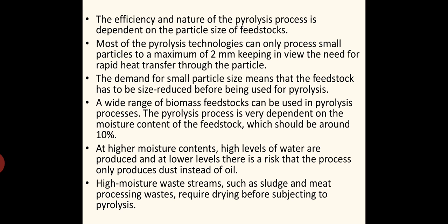The efficiency and nature of the pyrolysis process depend on the particle size of the feedstock. So in the pyrolysis process, we have to take care of the particle size, and make sure that the feedstock size is very small. Most pyrolysis technologies can only process small particles to a maximum of 2 mm, keeping in view the need for rapid heat transfer to the particles.